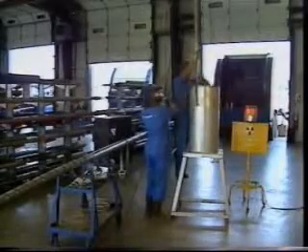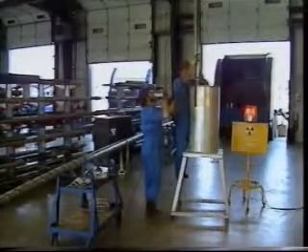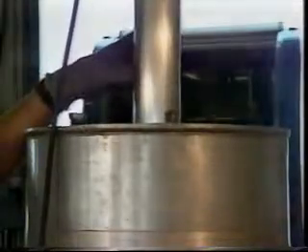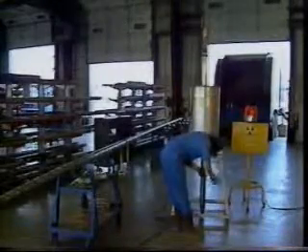Calibration of neutron tools is performed in water-filled tanks. The ratio of detector count rates can be computed and recorded for later well site sensitivity adjustment. At the well site, a field calibrator is utilized to reproduce the periodic monthly calibration value. As with all other tools we've discussed, these calibration records become a permanent part of the survey.